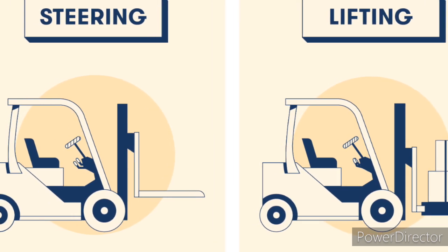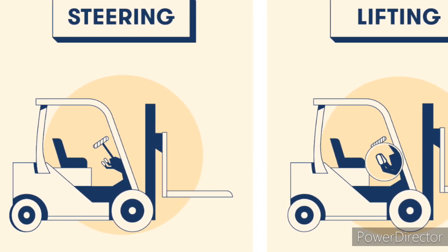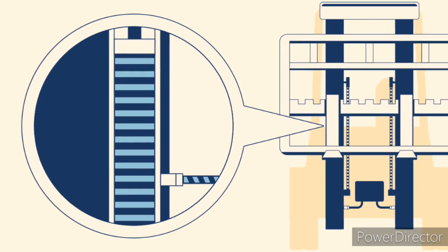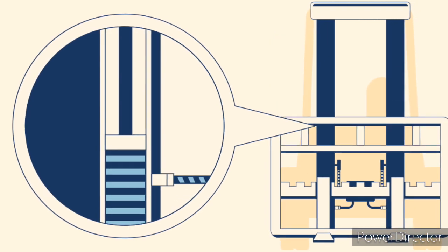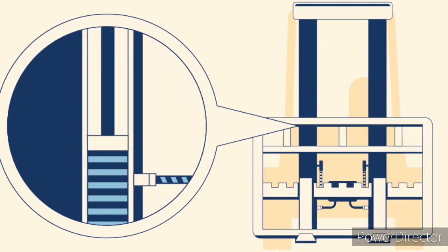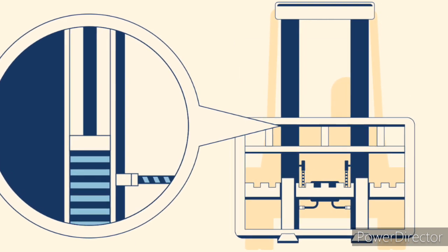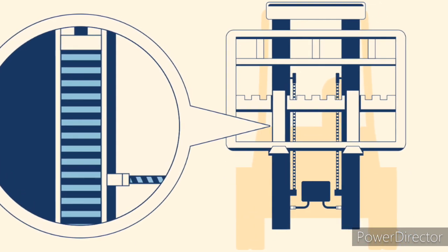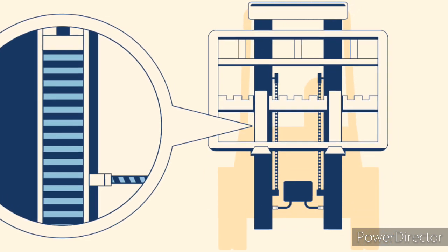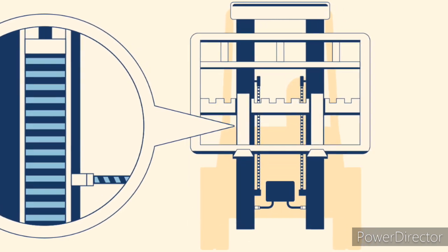When we operate a control valve lever, hydraulic fluid enters the hydraulic cylinder through the control valve, which allows it to enter without escaping. Pressure increases as fluid increases in the cylinder. Upward force is created when pressure is applied across the area of the piston head. The piston moves up as a result of the force below it. This increases fluid volume and decreases pressure. Hydraulic pistons push the masts up. Gears located on the mast are pressed against the roller chains. The masts move up and pull the fork up.